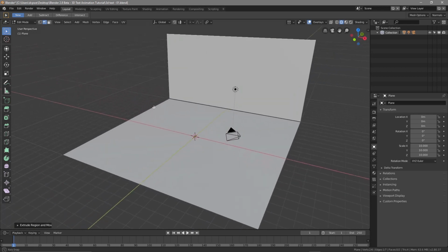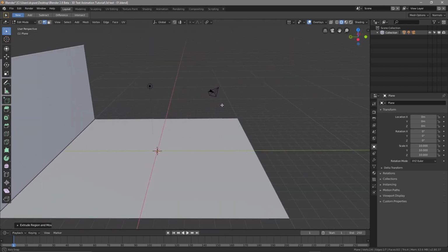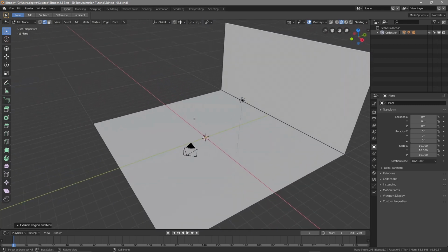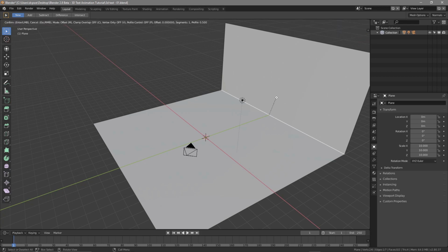Okay, we can rotate the object around, so we hold down the middle mouse button, we can rotate it around like this. Now, the next thing we're going to do is click again on this line here. We'll click on it one more time, and we're going to move our mouse to around here. So try and move your mouse cursor to this point here, and we're going to press Control B, and we're going to move our mouse wheel up, and that's going to create this bevel edge.